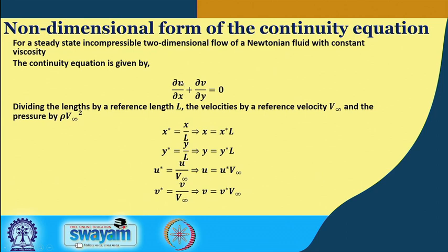So here we are assuming that the velocity has three components u, v, w, and we are taking the w to be 0 and two-dimensional. So we are neglecting all the z differential, that means we are taking w to be 0 and we are taking all the dou by dou z terms to be 0. Okay. So with these assumptions, we are writing the continuity equation like this, and also because it is incompressible,